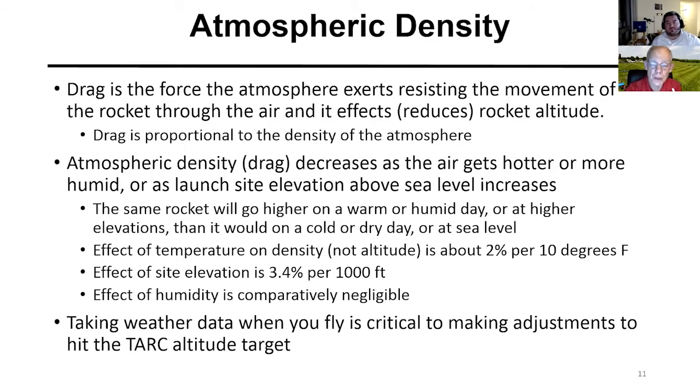So make sure you take weather data when you fly. Humidity doesn't matter, by the way. Temperature matters. Barometric pressure doesn't matter very much within the normal range. If you're flying in some kind of tropical depression where the barometric pressure is really, really low, the wind's probably really high. So normal ranges of variation in barometric pressure and humidity don't matter. Temperature does matter a lot.